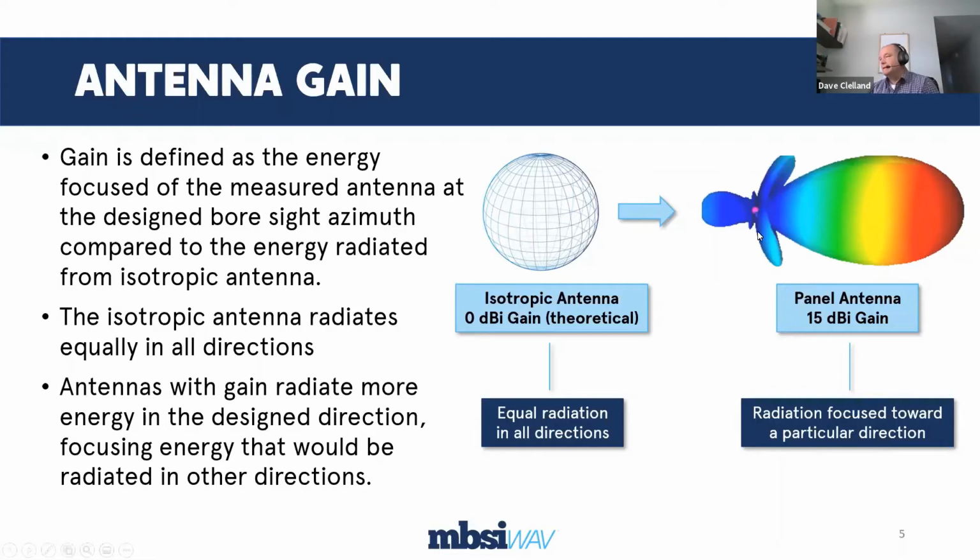Depending on where you are in relation to the antenna determines how much energy you can actually see from the antenna. This characteristic is really important to remember when we're building an antenna system on a tower and we're co-locating equipment together. There is energy that comes off the back of the antenna, off the sides, out of the top, and out of the bottom. It's just that there's more energy radiated in the direction the antenna is designed to go rather than all the other directions. So how much of that energy there is becomes important as we estimate performance together.